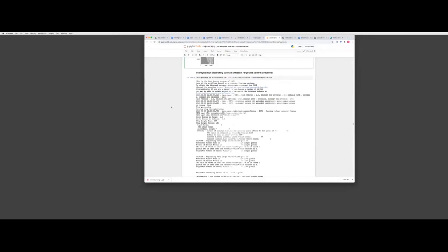So we want to account for that delay and refine our offsets to sub-pixel accuracy. For interferometry, remember that you need to have the pixels registered to at least 1/10 of a pixel. Usually, we aim for 1/100th of a pixel accuracy in registering the two SLC images.